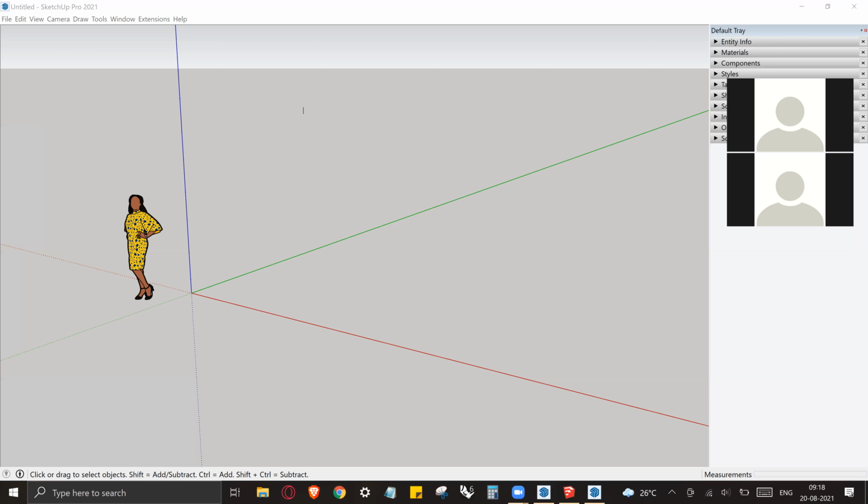Now, first thing, as soon as you have opened the SketchUp window, come up here and you have to go to your View tab. In there, you have to go to your toolbars, and then guys, from your tools, you can turn on your large tool set as well as your shadows and also your views. I will show you how you can do this as well.